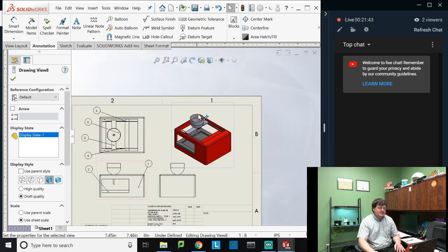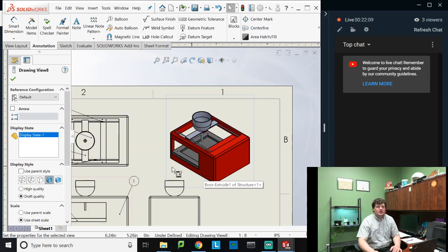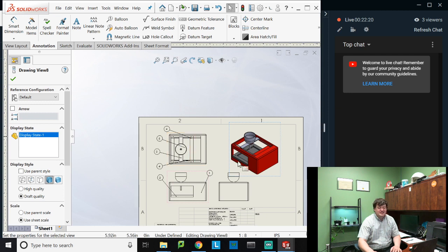What this does is this allows us to say what parts comprise this assembly, where are they located. A lot of what the sheet shows is what this is supposed to look like, where all those parts are supposed to be. There's no real good way of showing how things are connected unless you want to do an exploded view, which I can show you how to do too. There's not a really good way of showing how the parts fit together in 2 dimensions for a 3-dimensional object. So we have to do what we can. Showing the part numbers is needed. On all good drawings, they will always show the part numbers.